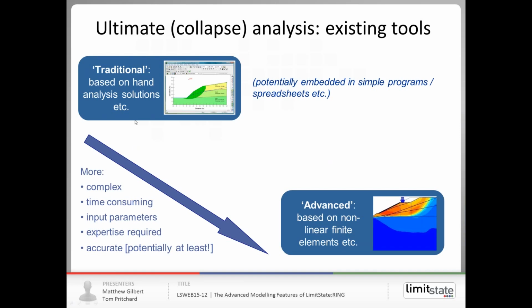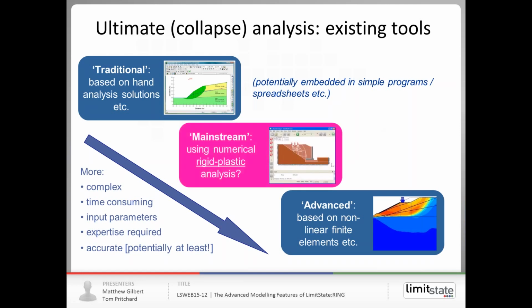The problem has been historically there's been quite a large gap between those two types of tool, and what we're focusing on at LimitState, springing from work carried out at the University of Sheffield, is developing what you might think of as mainstream tools which sit in the middle, which use numerical rigid plastic analysis and bring many of the benefits of hand calculations, but also many of the benefits of advanced methods in the sense that you can apply the techniques to arbitrary geometries and the like.